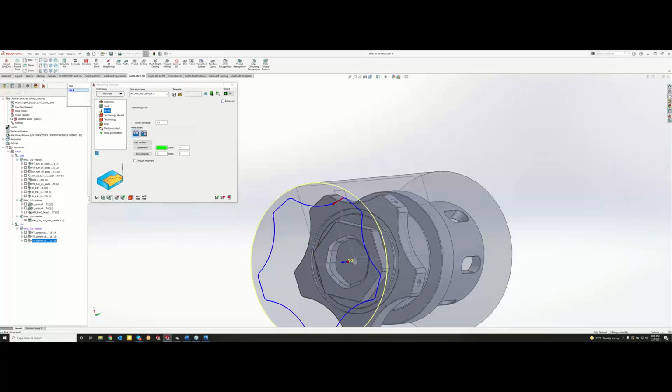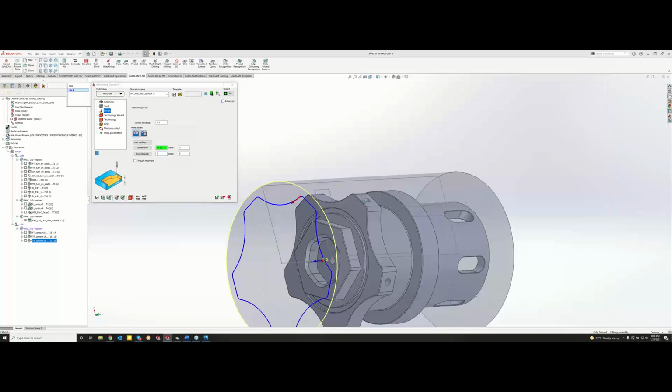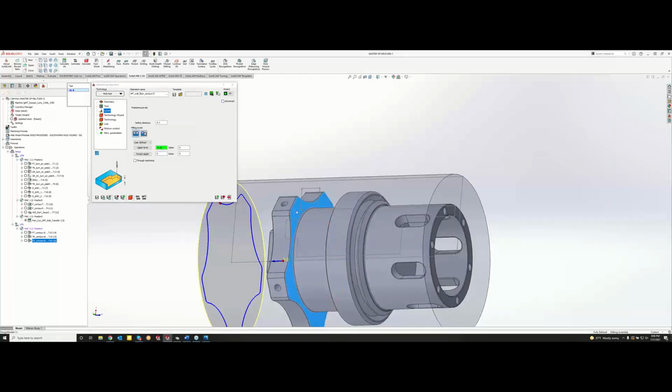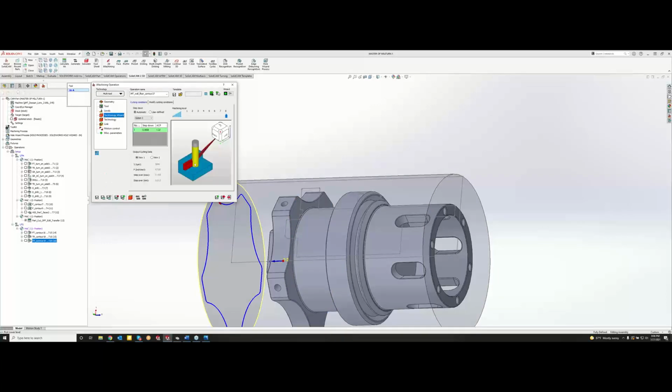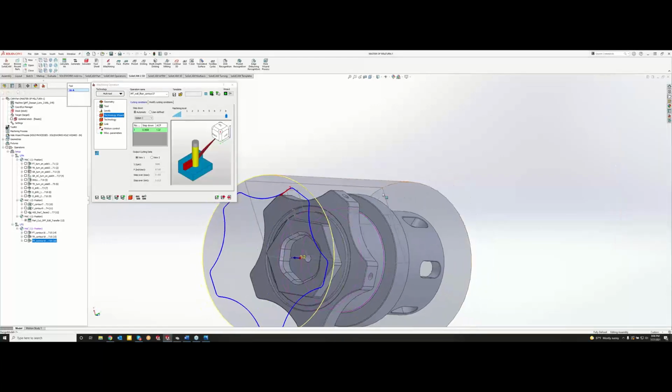Oh, actually, no, I'm sorry. I got this wrong. I'm doing this back border here. So that's my start. And then my end, flip my part over, grab that, and we'll tell it go an additional 20 thou past. Okay. And we're using iMachining level 8. Save and calculate here. And let's see what we got.